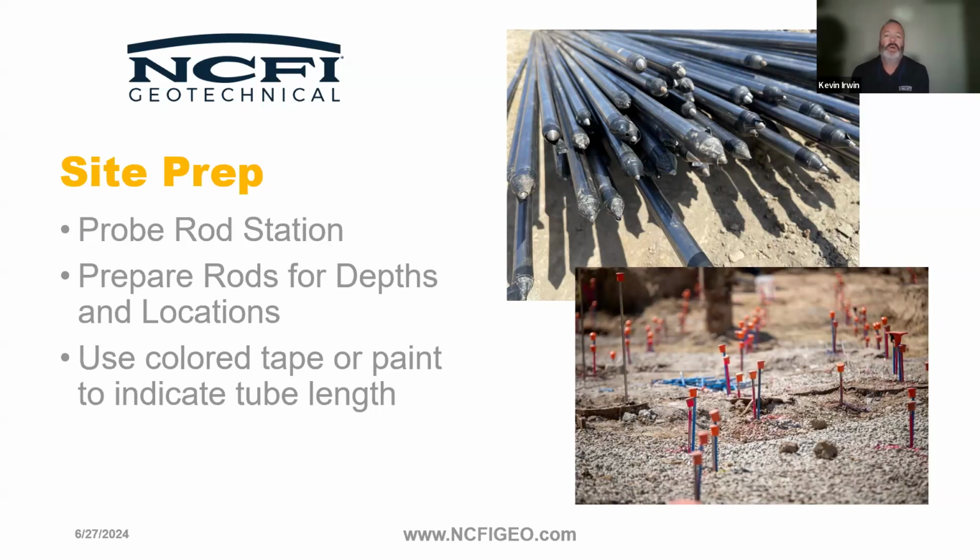For those of you who have lifted a driveway or a sidewalk or some type of a slab with polyurethane foam, that's a pretty straightforward and easy process. I mean, I get on site, I drill a hole, and I pop the injector in and begin shooting. It's a little more involved than that, of course, but there's a lot more preparation that goes on the operations side with deep injection. You can see the probe rods there. Those are half inch or 5/8 steel tube.